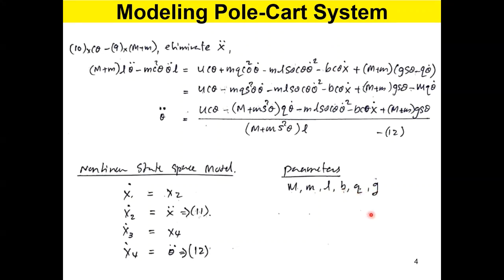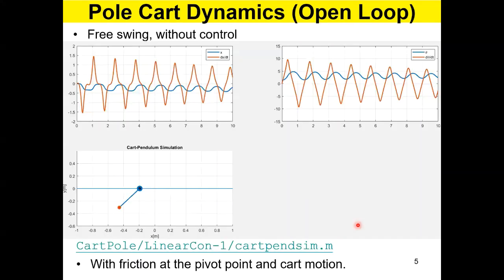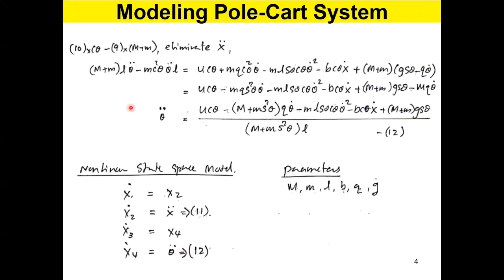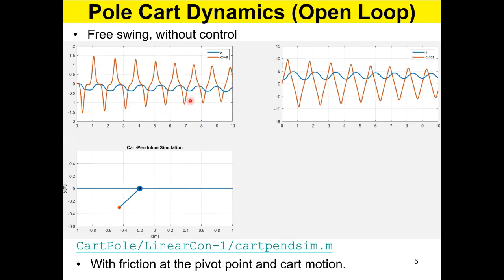Okay, right. Now, when you have the system model like that, the first thing you need to do is to go to a simulation platform like MATLAB and write down these codes, because we have the two equations, right? Explaining the motion, x double dot, theta double dot. So you can start from any point, right? Any x double dot, any theta double dot, okay, as initial conditions, and then run these two equations and see what happens. Okay, so